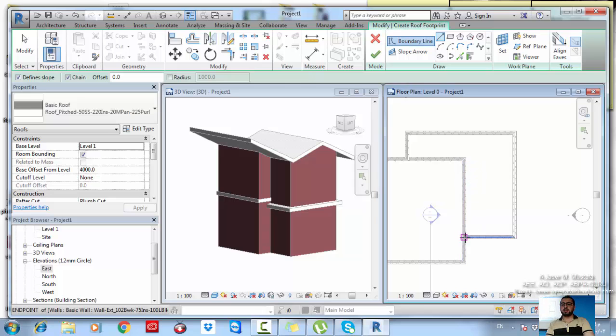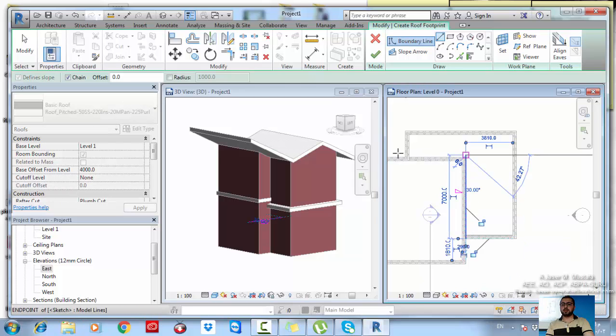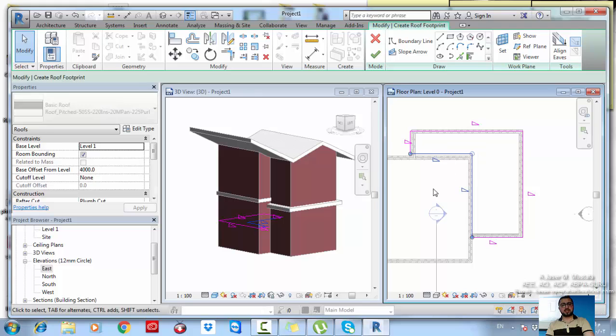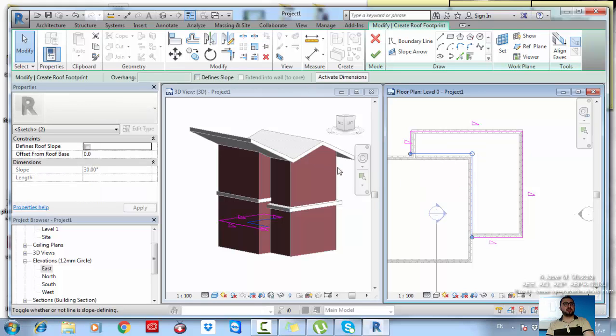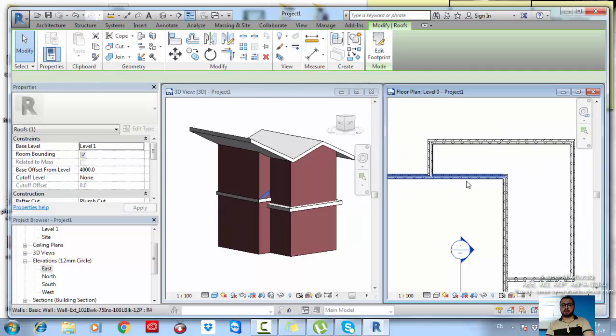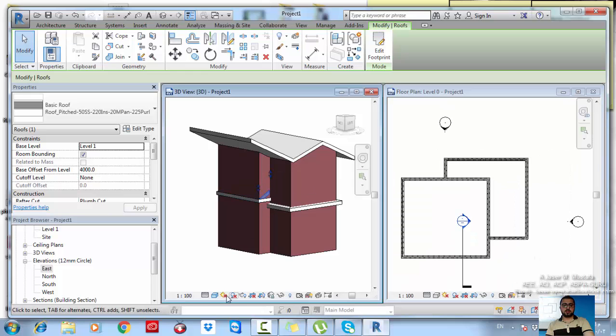How? You can just draw the lines, for example, this way, okay, and make sure that your lines are accurate on the edges, but now I don't mind for that. You can just select these 2 lines and make it without slope. You can also select this one and this one, because the slope will go this way and this way. Click define slopes, for example, and just click OK. Let's isolate this one or delete this one.